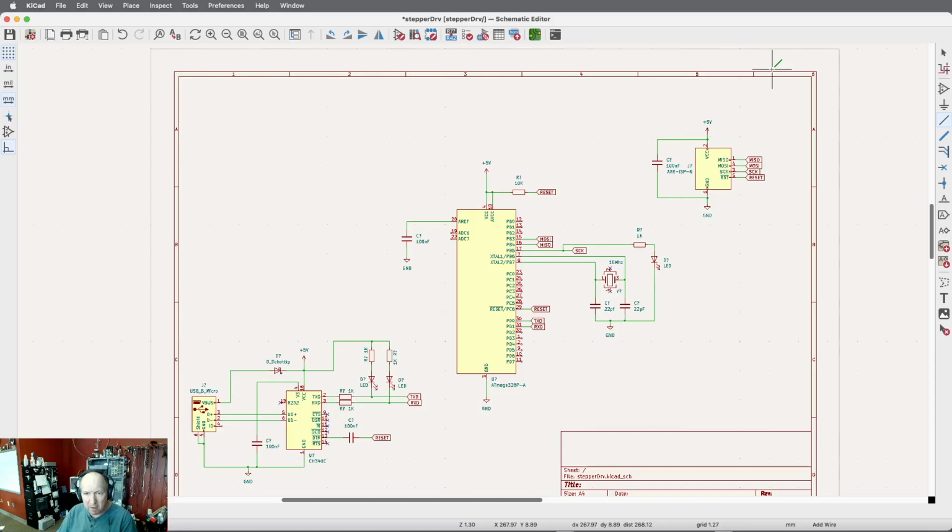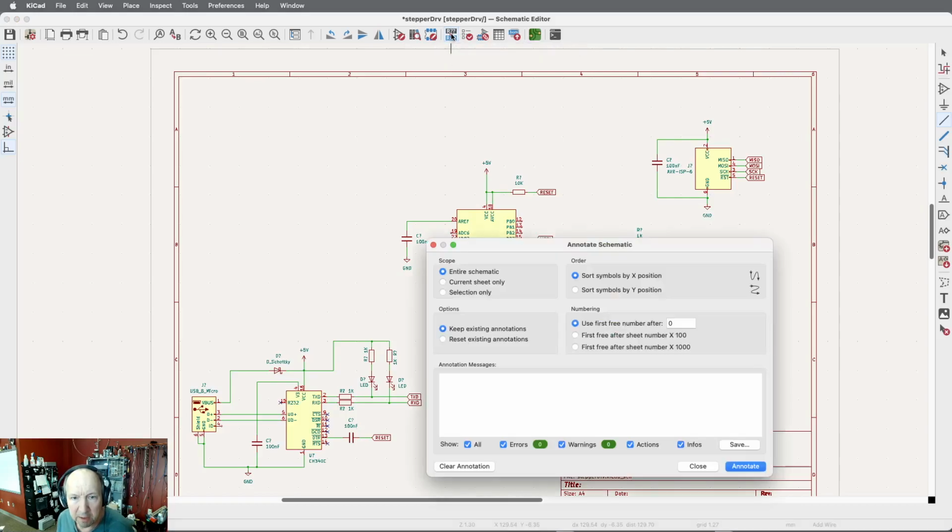So there is our basic schematic. This is everything we need. Now, the resistors and caps and stuff are not labeled yet. So we need to fix that. Up here on the top, let's see what we got. Symbols, create, edit. There should be one for, oh, there we go. This one says, fill in schematic symbol reference designators. Okay, which I believe will do what we need.